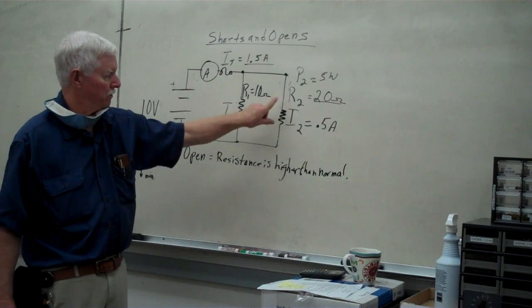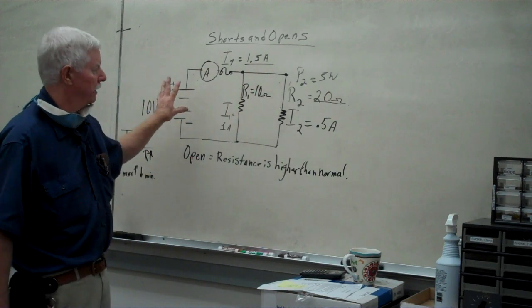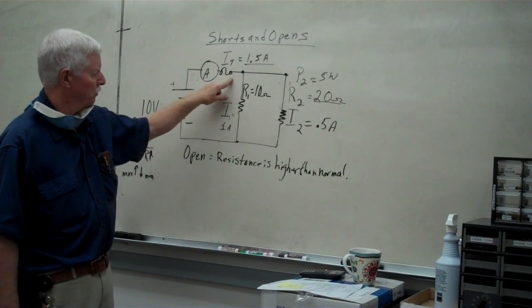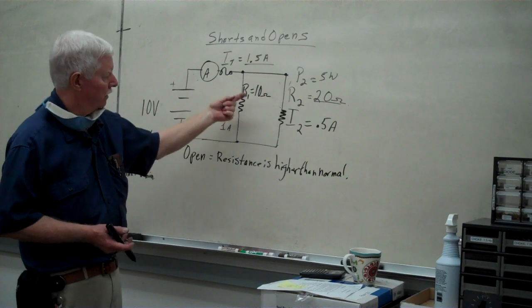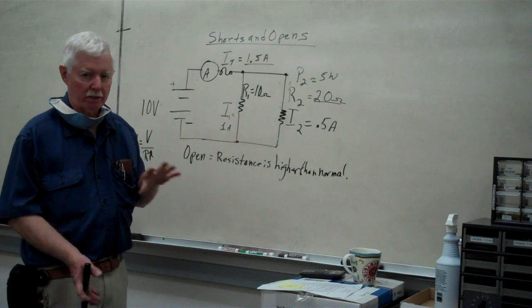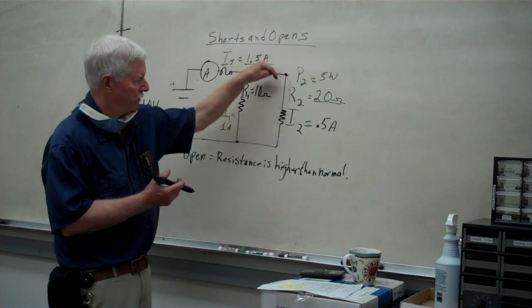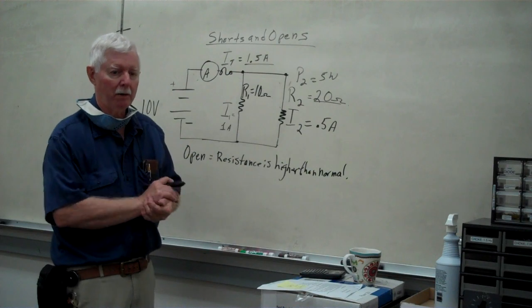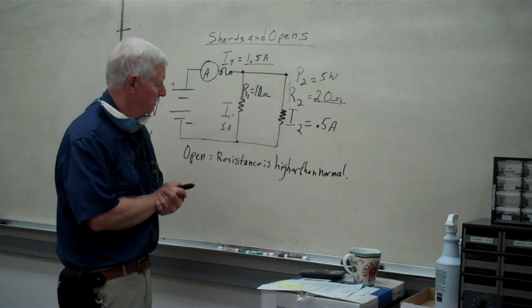Now usually when this is occurring, the other branches aren't affected. As long as the power supply is in good condition, all of the series elements are in place, and the fuse is working, the other branch currents should be just fine, as long as this particular resistor is increasing in its internal resistance. Its branch current is going to go down, but it doesn't place a load on the total amount of the power supply feeding all of the branch currents.